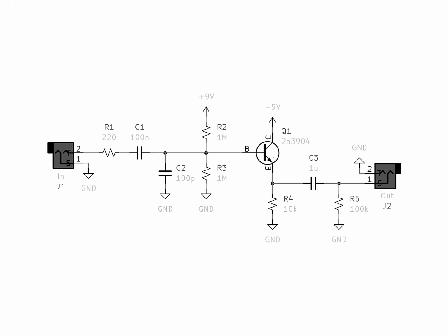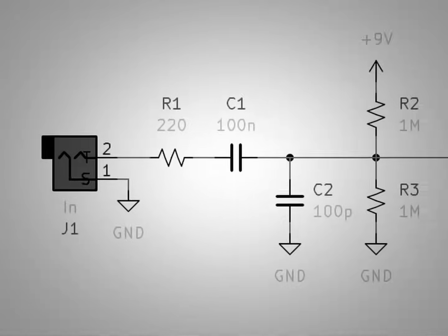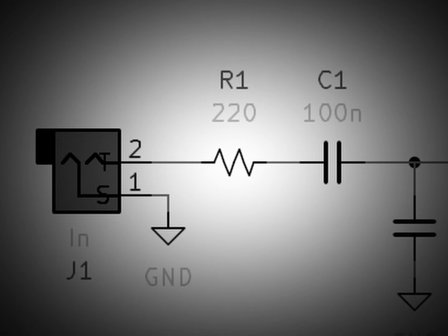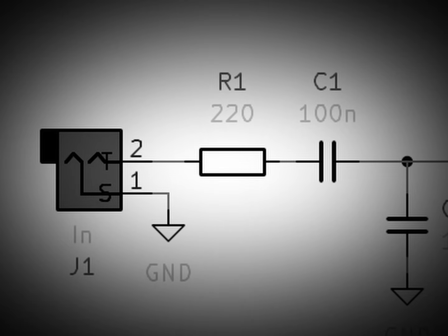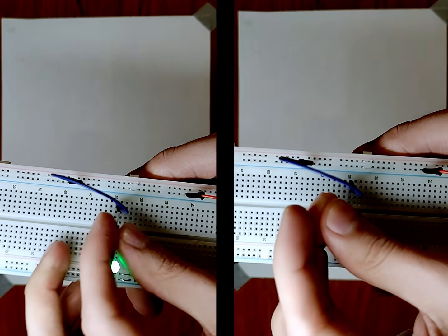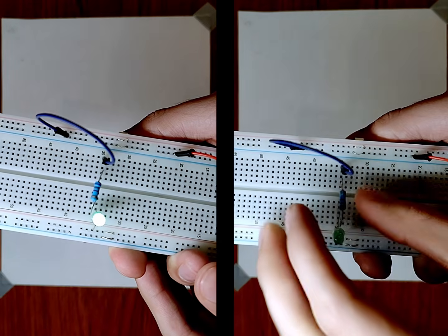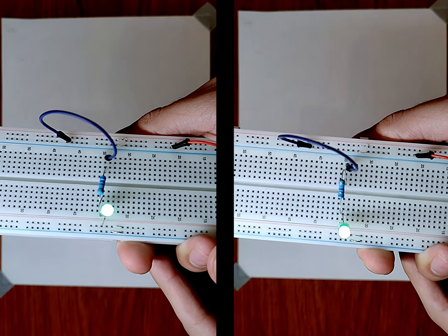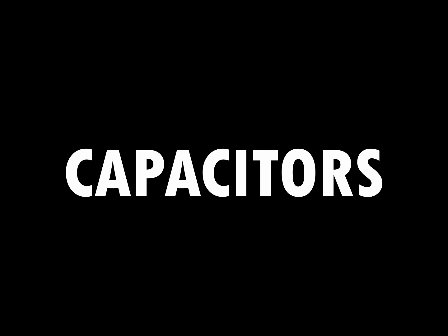In a schematic, resistors are represented with this symbol, a squiggly line that makes our electrons zigzag around, making it harder to get to the other side. Or as this boring box full of nothing, if you care about international standards. It's super easy to map these to the real thing, as they aren't polarized and thus the orientation you place them in a circuit doesn't matter. But the same cannot be said for...